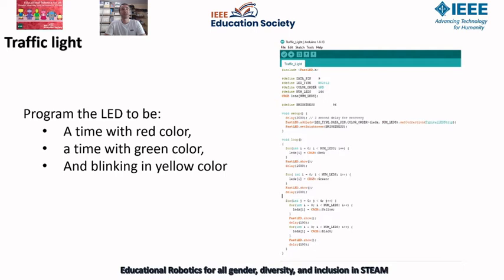As you can see, we are defining the data pin for the port 9. We are choosing an LED type as WS2812 and the color order as GRB, and the number of LEDs has to match with the LED strip. We are using in this example a 144 LED strip, and we select the number of LEDs as 144.